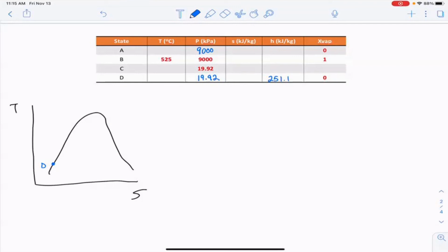All right. Now, as we look at this problem, you can start to figure out what the enthalpy is at those different stages. So let's do this first. So we knew this is B, and the state at B hasn't changed. So we still know also that B is 3448.7. Okay. So now our challenge is to figure out where is A in terms of the enthalpy and where is C in terms of the enthalpy.